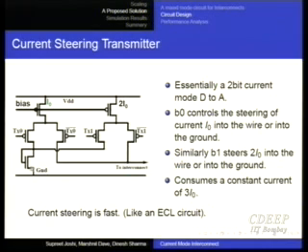Okay, so I size this transistor so that the holding voltage here is the same as the interconnect voltage, which is Vref, right? So size this transistor to be very close to Vref. Then the current flowing is always the same and the drain voltage is always the same, whether it goes this way or that way. Therefore the source voltage will always be the same. So as a result, these 2 transistors are identical. So either this transistor is on or this transistor is on, right? And the drain voltages are also the same.